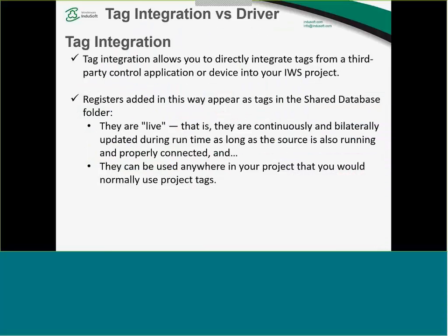The tag integration allows you to directly integrate tags from a third-party control application or directly from the PLC into your InduSoft Web Studio project. So you don't need to reconfigure that. All the registers that you add using the tag integration are going to be live. As soon as you start the runtime, you're going to start communicating.